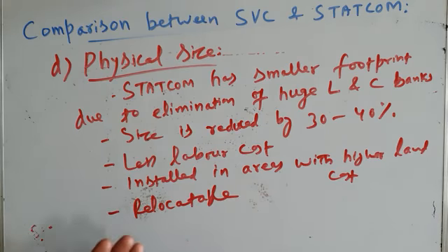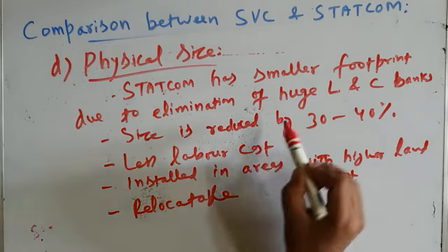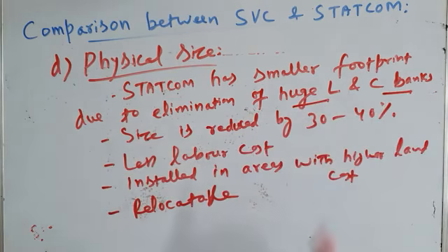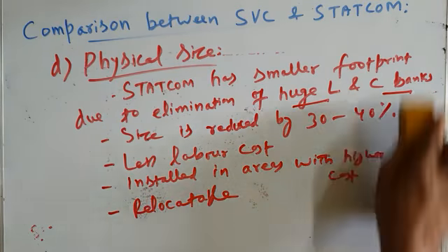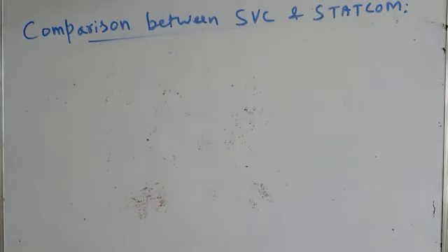It is relocatable, whereas the SVC is not relocatable because the size of SVC is very, very large. It occupies larger land because of large inductors and huge capacitor banks. So from the point of view of physical size, labor cost, and the feature of being relocatable, STATCOM has an advantage over SVC. Next is